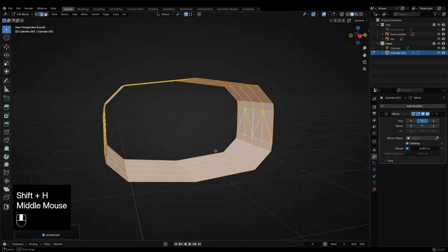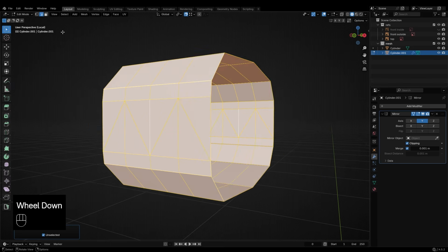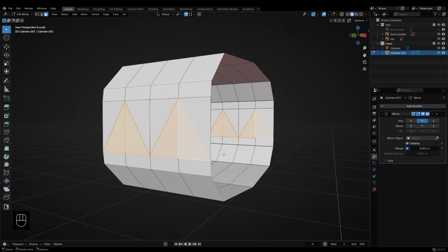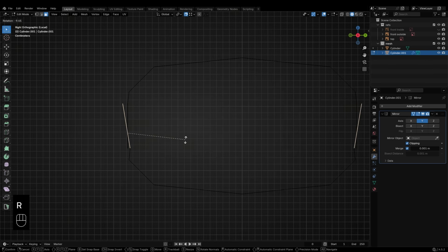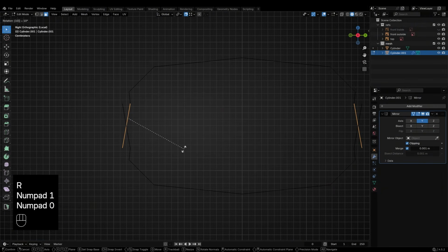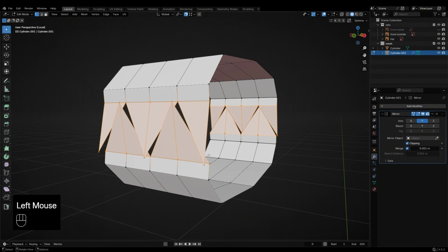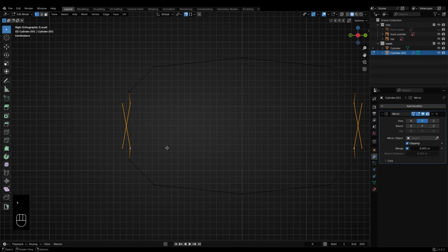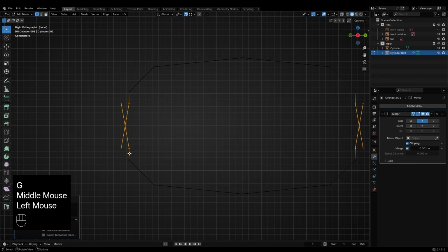Next, select the cover face area in the middle. Then select the 2 triangle faces at the bottom. Switch to right view, then rotate them by -10 degrees so they open outward. This depends on your current view orientation. Do the same for the triangle faces at the top. Then select both triangle faces, go to right view, and align them with the bottom vertices using Vertex Active Snapping.